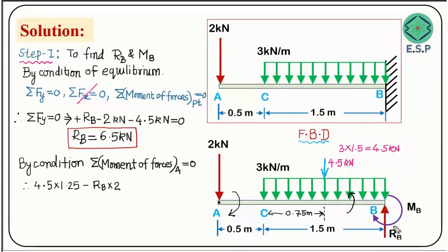And if you look here, there is a moment acting at this particular point, which is a clockwise moment. So this clockwise moment will create clockwise rotation about this point. This point is fixed here, so we have kept this point free. So you will see, if you apply this kind of moment, your beam is going to tilt or rotate something like this, because this point is free. Getting or not?